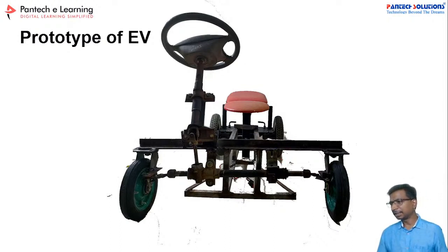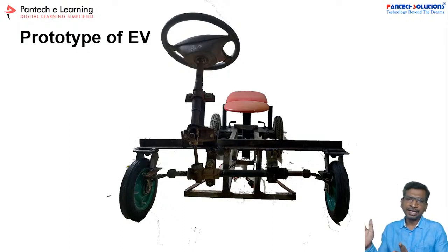Why are battery standards 48 and 72 volts for EVs? 48 is the earlier version. Nowadays they come with 72 volts, because as you increase the power rating, 72 is the typical voltage range for the traction motor. That's why people keep the 72 volts. But many luxury EV vehicles come with 360 volts.